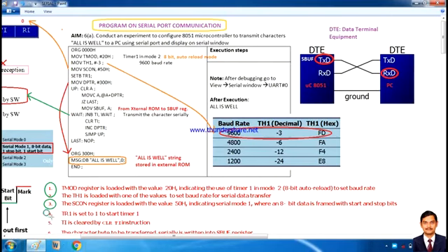Next, let us look at the next parameter. TR1 is set to 1 to start the timer. In order to create this delay for the 9600 baud rate, the timer has to be initiated. Set TR1 with this instruction.